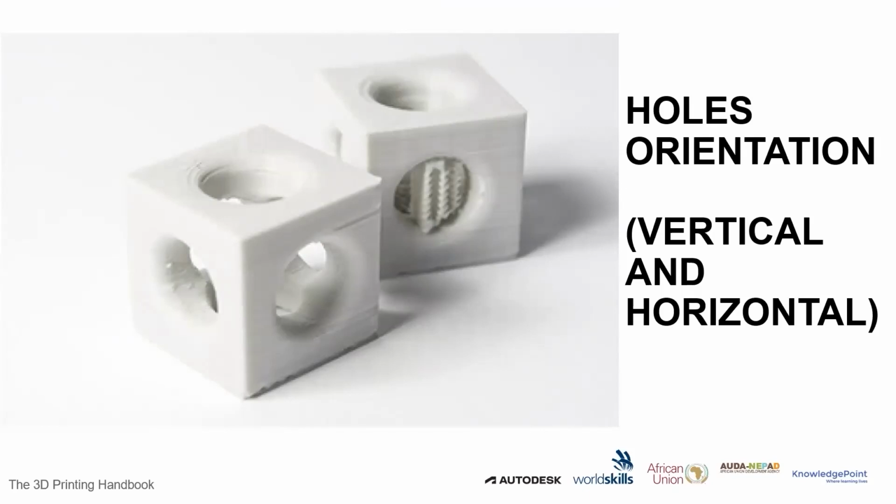So in here, if I have a hole at this point, this particular design will really require some sort of support, otherwise it might start failing if I don't use support. But it's also important that if I'm printing on top here, you see that the surface in here didn't come out well. But if it is a small hole, practically less than 5 mm, 10 mm, then you don't really need to have support.